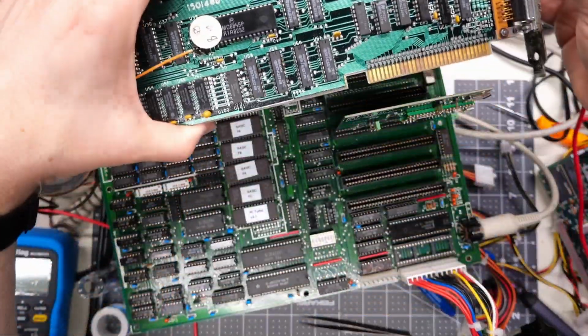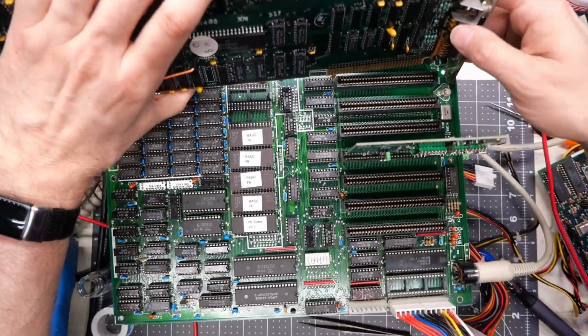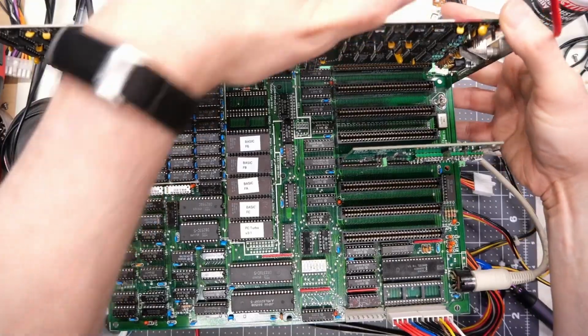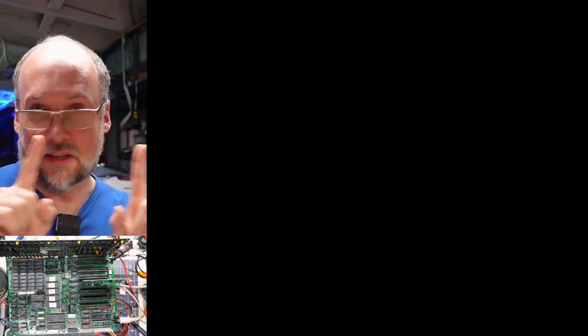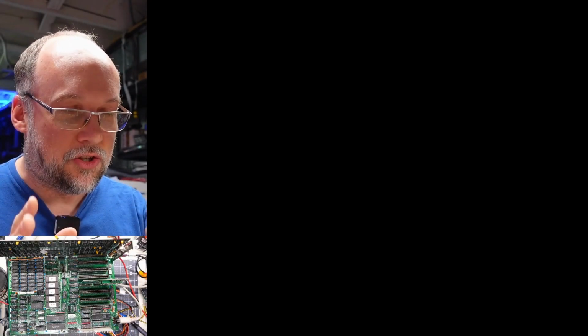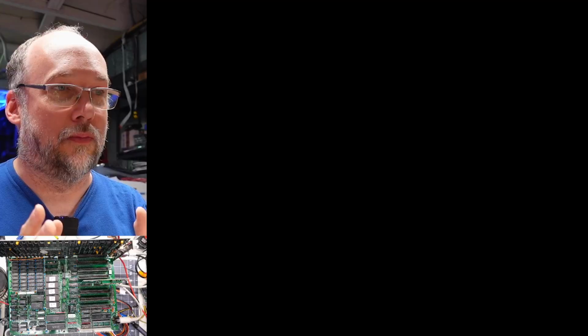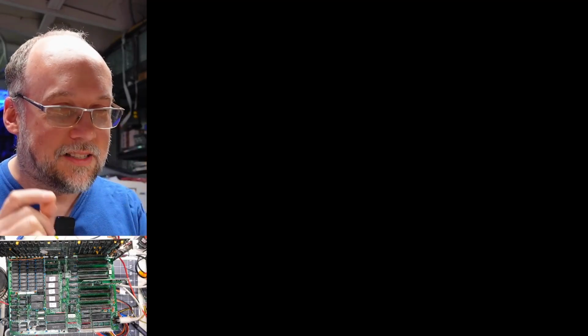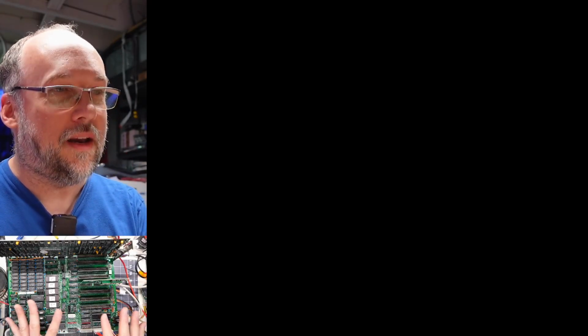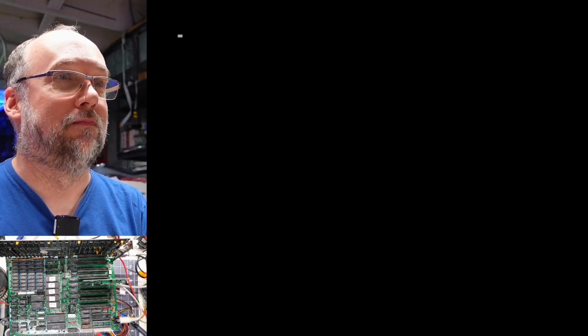So I have no idea if this is actually going to work or not. This might result in some kind of weird artifact as well. So I may need to undo that. I don't think this should have any effect on the border region or the overscan and stuff, like when I made that first mod that didn't work. I think this should just cause it to speed up and create some more snow. This is very similar, if this works, to the fast vid or the speed up hacks for the original Commodore PET. It's just doing it in a way that doesn't create a bus conflict and that doesn't destroy things.